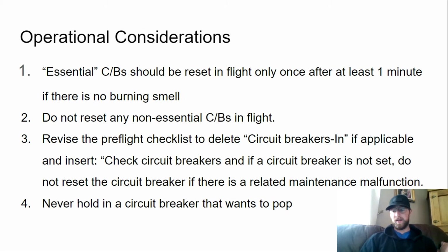There was actually an incident where a crew reset the in-flight weather radar circuit breaker. Prior to their flight, it had popped without them knowing it, and this crew reset it, and they believe it ended up leading to a fire because they reset that circuit breaker. So if you get in the plane and a circuit breaker's popped, investigate it a little bit. Don't just willy-nilly pop that thing back in.